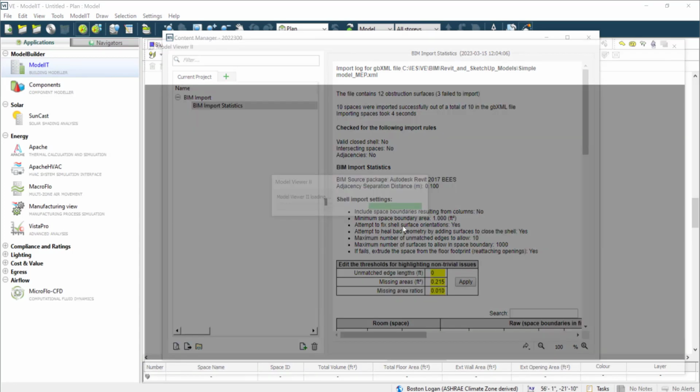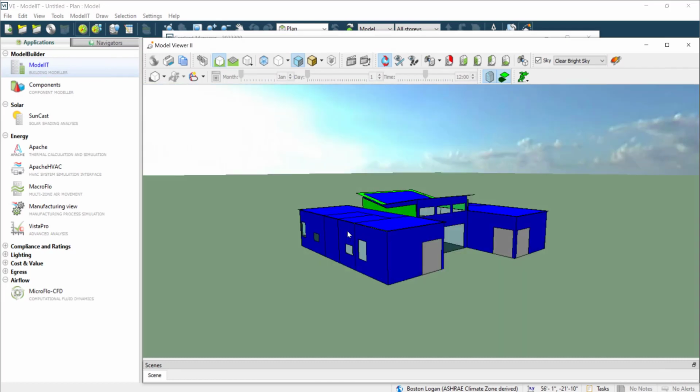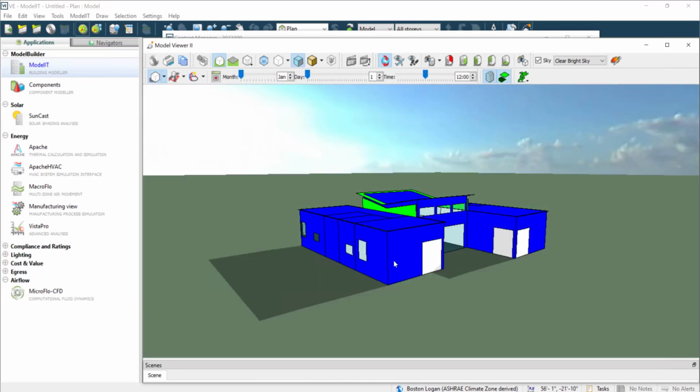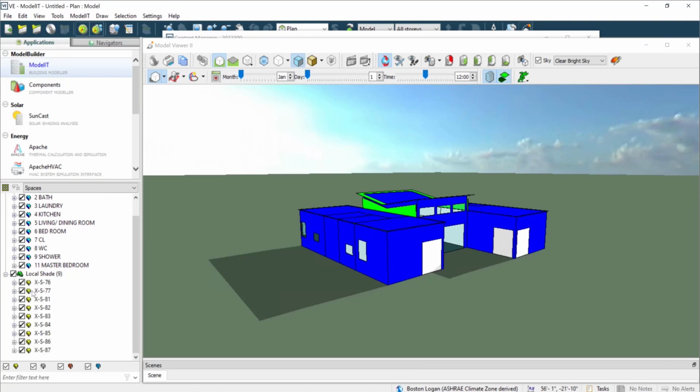Best analysis you can do is a visual analysis. So what I mean by that is if the geometry was bad, what you would see is a missing wall. Like you would be able to see into that room. The important little trick here is what you're looking for is a list of rooms here. If they weren't picked up as rooms, they would be shades. In other words, just a wall patch almost touching another wall patch, but that's not a room. A room needs to be sealed or watertight, and that's what's going to give you good results.